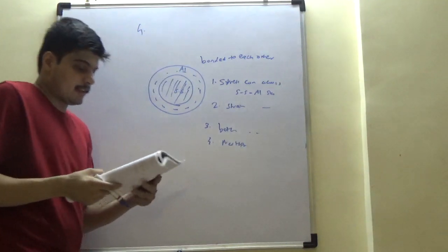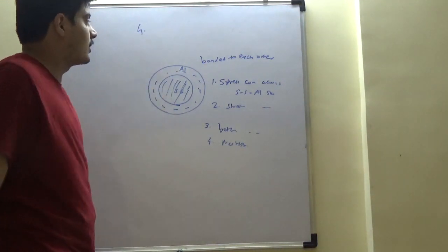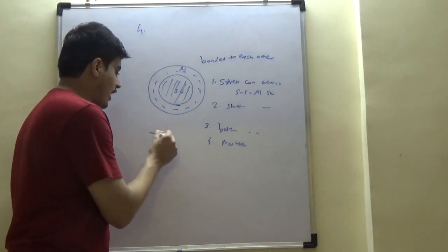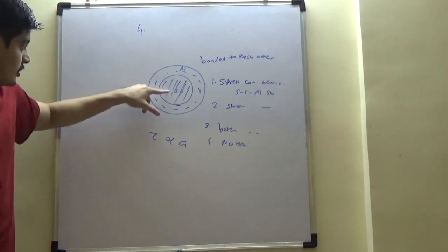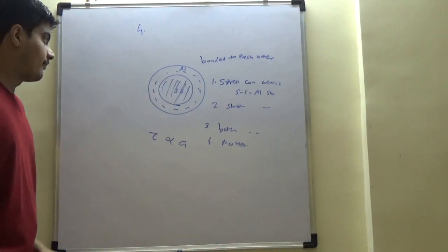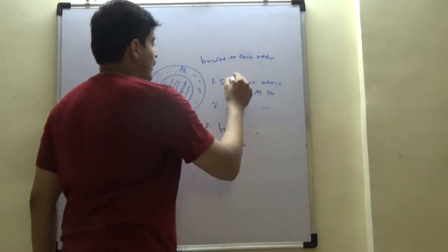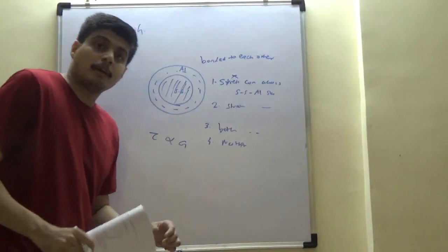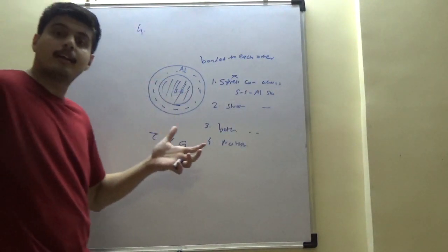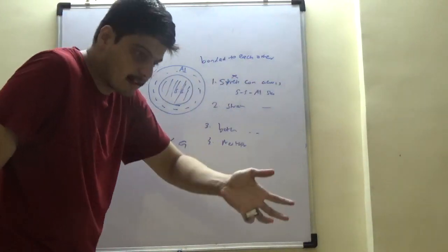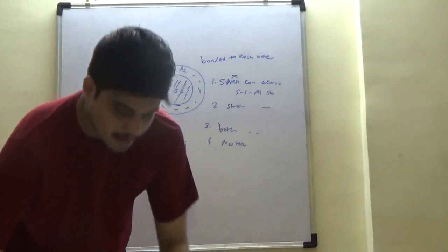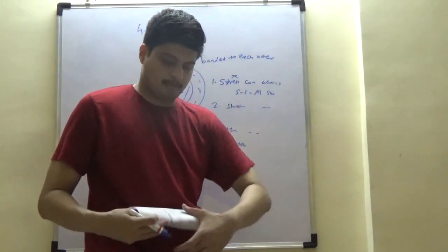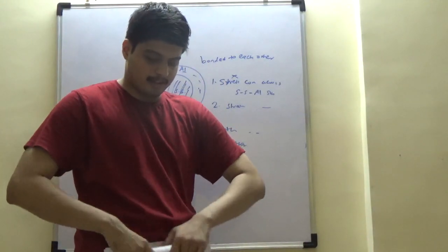Now, the shear stress depends on the property of the material, right? Tau has a proportionality constant G, and the G of these two are different. So shear stress can never be constant, but they are glued or bonded together, which means the twist they are going to experience has to be the same. Otherwise, we can demonstrate it this way.